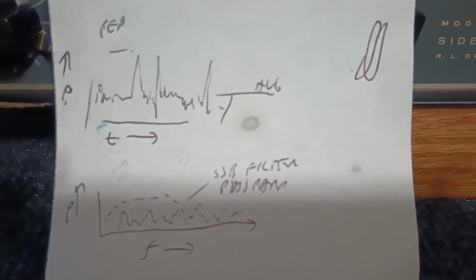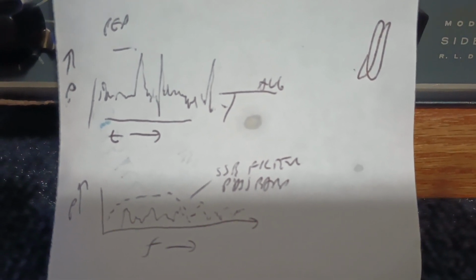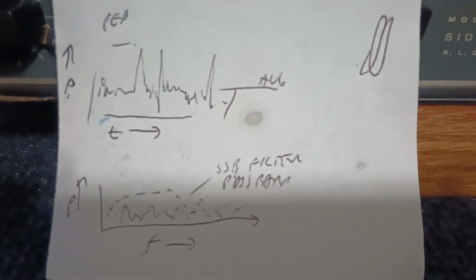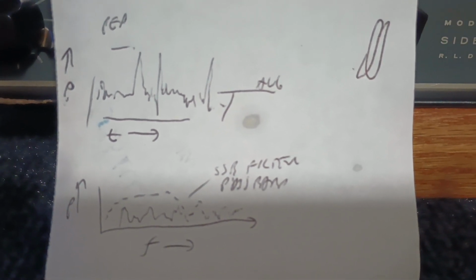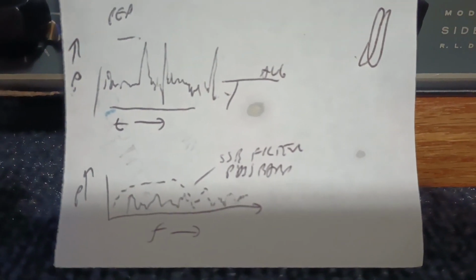Those peaks are pretty much useless to speech, and there's no use in speech with a puff of air in the microphone that makes a spike. So take the peaks off, and don't clip them because that causes distortion, but roll them off. And that allows raising what's marked as average, AVG, up to the peak level for far more transmit power. That's one thing processing does.